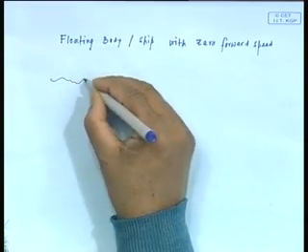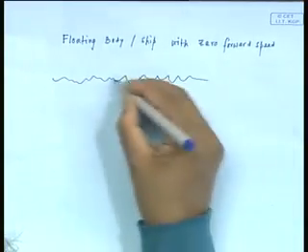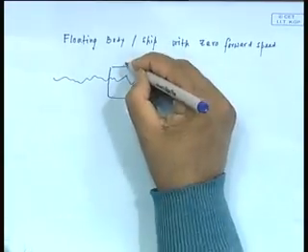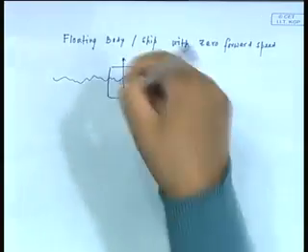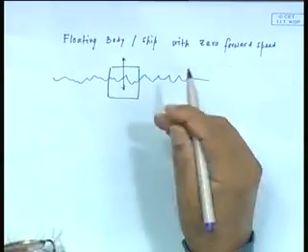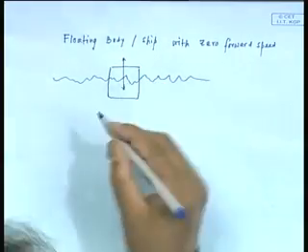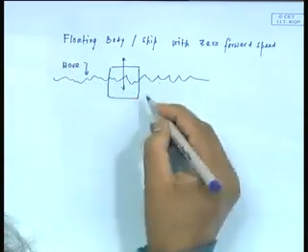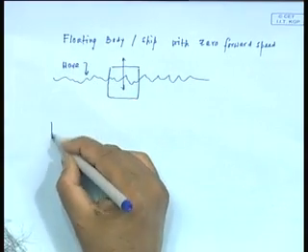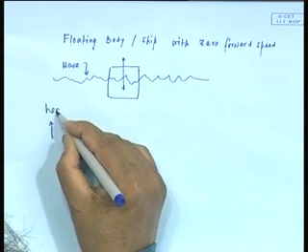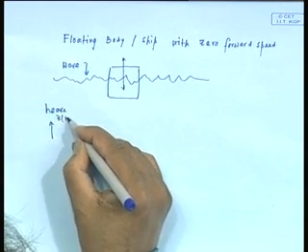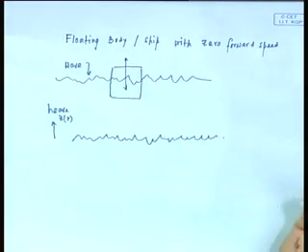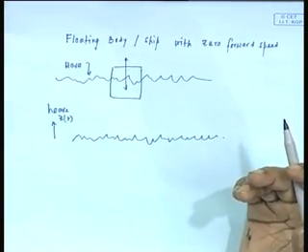Now, let's take this example. I have this wave and I put a body. Now, I am measuring its heave motion. I have a stick, I measure heave motion. How will it look? Well, if you take the response z, this is the wave, and this is the heave motion, z(t). It is also going to look random, naturally, because random input is going to give me random output.